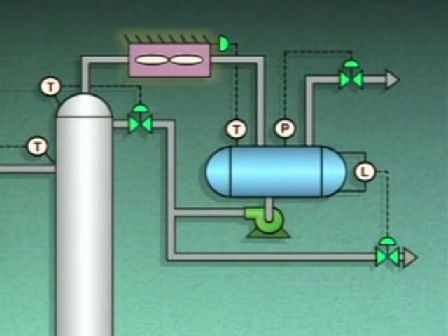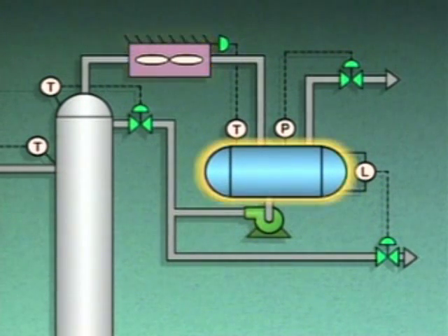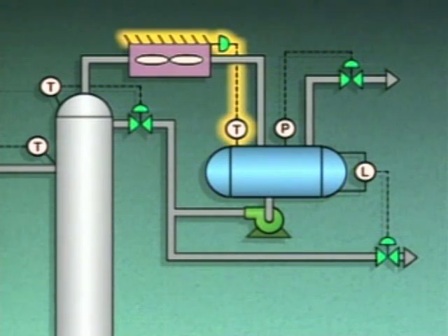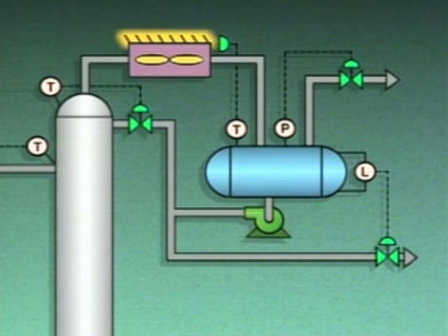As the additional vapor is condensed in the condenser and flows into the receiver, the temperature of the liquid in the receiver increases. The condenser temperature control loop senses the increase in temperature in the receiver. This control loop then adjusts the louvers in the path of the forced air from the fans in the condenser to cool the increased amount of vapors.